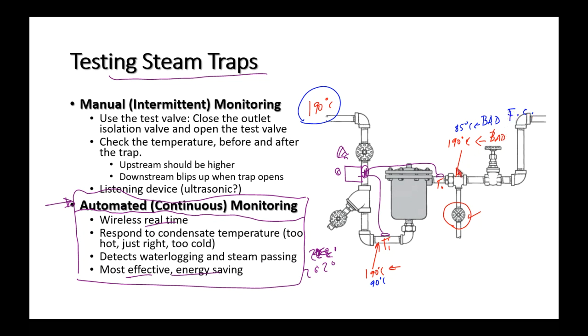What we have there is a trap that has failed closed. Okay, and so now it's waterlogged and it's backing up condensate, and the condensate's residing in there for so long that it has a lot of time to dissipate heat and cool off.